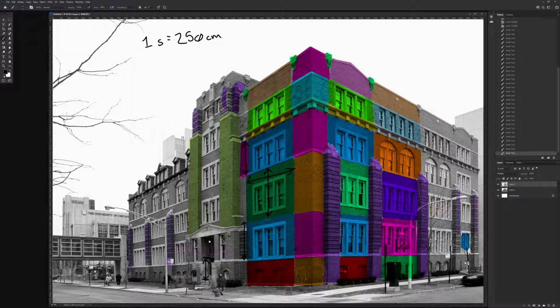I'm also going to make this lower story, which is part of the basement and actually disappears underground. I'm going to make this the height of the door, which is 200 centimeters. So our basement is going to be equal to 200 centimeters. And this gives us the ability to make a little bit of variation in the building so everything is not exactly the same height, and still make it look interesting and accurate.